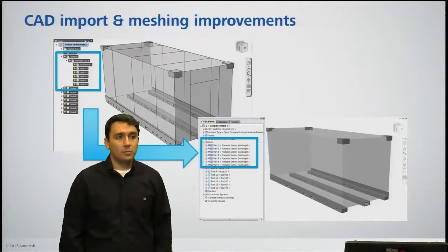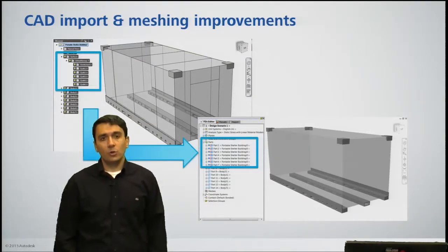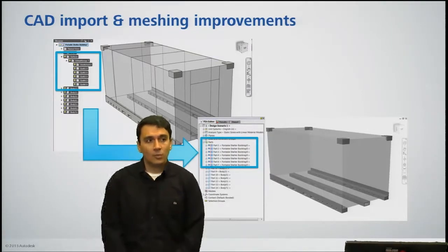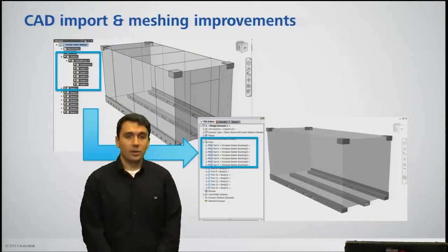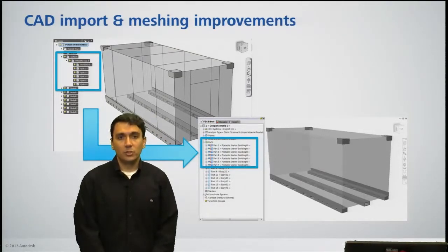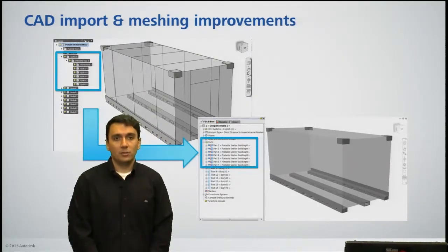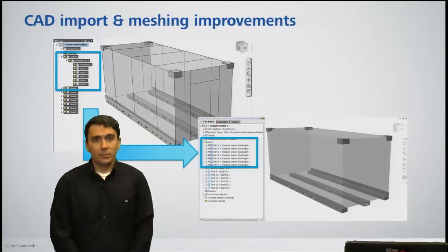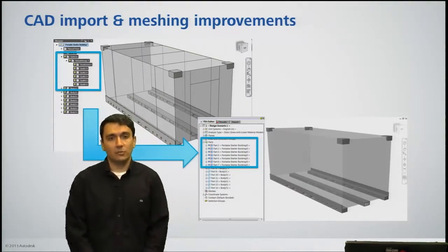We've done a couple other improvements to meshing, and the second one is around part imprinting. So if you're dealing with a surface-only geometry and importing your full assembly as a single part, we've implemented a new feature called imprinting within parts. This is especially beneficial when you have two adjacent surfaces coming together and you want good mesh matching to get accurate results.